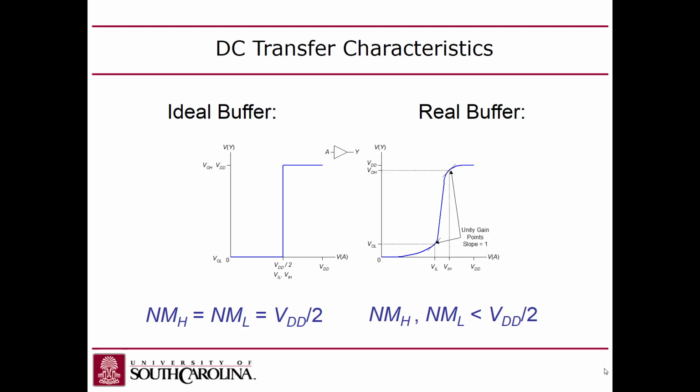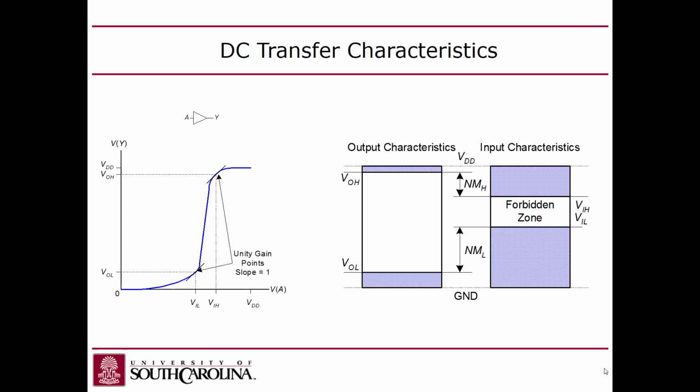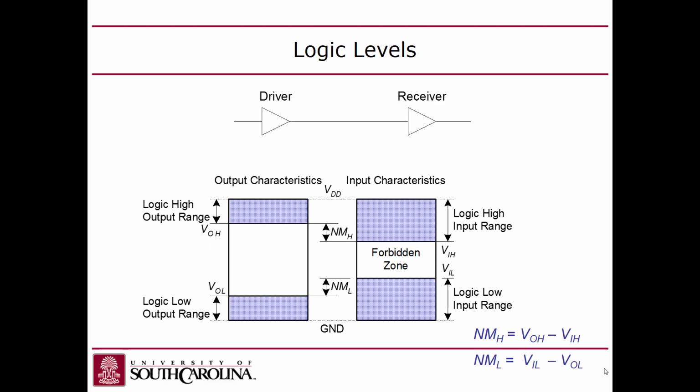Now, why are we talking about this? Well, because this seems like more of an electrical engineering type concept anyway, right? It's kind of an electronics thing. Well, it has implications for computer architects because as you lower VDD, you also reduce the noise margin, meaning that the circuits are more susceptible to noise, meaning that it becomes more likely that you're going to have an error.